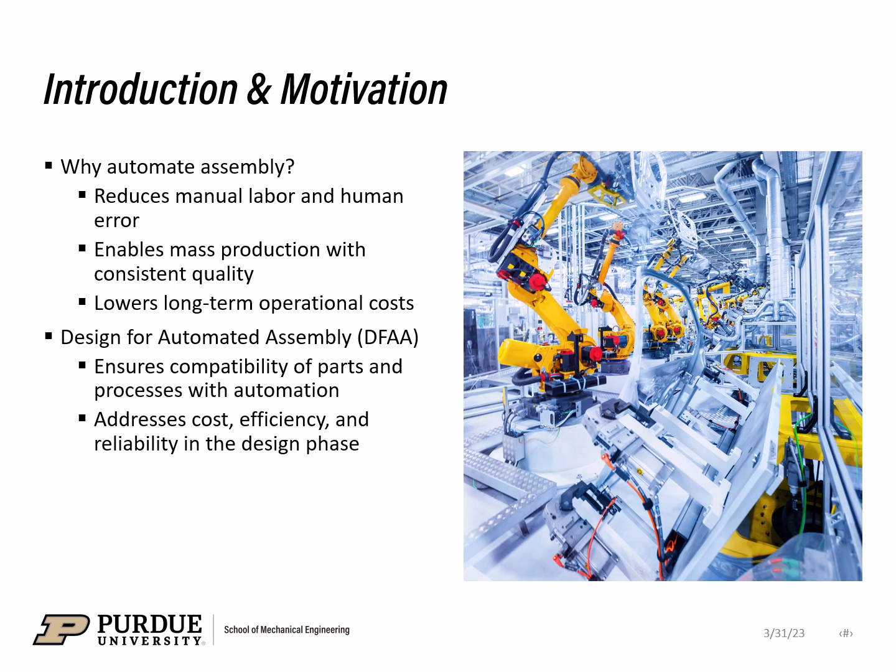Could you simplify the geometry? Could you add different alignment features? Could you eliminate fasteners entirely? All of these kinds of design considerations must be brought to the forefront when considering automation design. However, these principles are very similar to those described in design for manual assembly, but the designer must consider that a robot gripper or robot tooling is performing the tasks instead of a human.